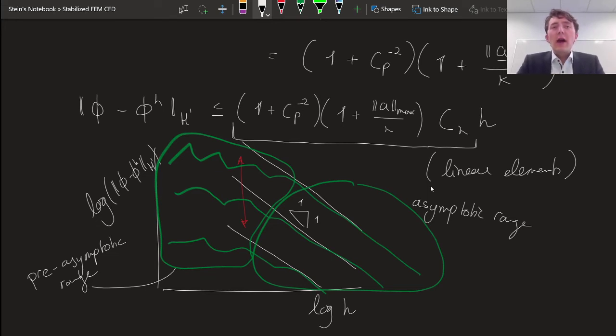So that is where our error is not dominated by an interpolation error, but rather by a problem with our numerical scheme. In this case we have an unstable finite element method, and the error that we introduce due to the instabilities in our finite element approximation is much larger than the errors introduced by the fact that we're using a finite basis, which has to do with the limit of how well we can interpolate any solution in our finite element mesh.